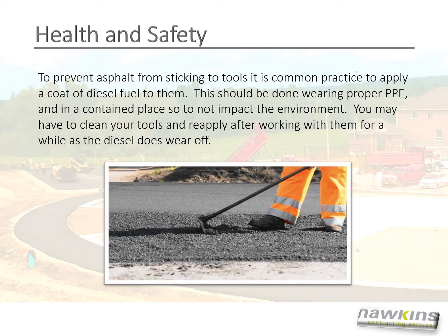To prevent asphalt from sticking to tools, it is common practice to apply a coat of diesel fuel to them. This should be done wearing proper PPE and in a contained space so as to not impact the environment. You may have to clean your tools and reapply after working with them for a while, as the diesel does wear off.